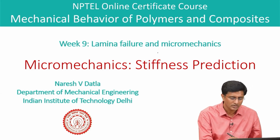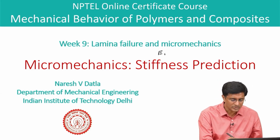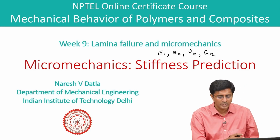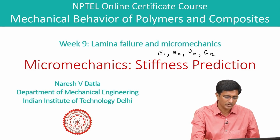So when we say that we are looking at the stiffness prediction, we are essentially trying to predict what are the stiffness properties of a lamina, which include the stiffness along the fibers E1, perpendicular to the fibers E2, the Poisson ratio nu12 and G12. So the idea being, can we predict these if we know the properties of the fiber and the matrix? So we'll start with E1.